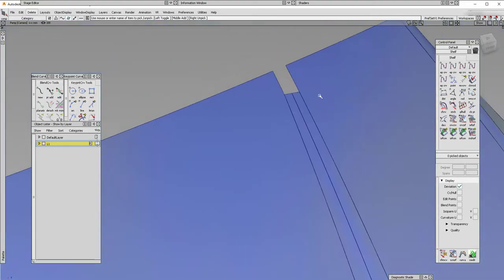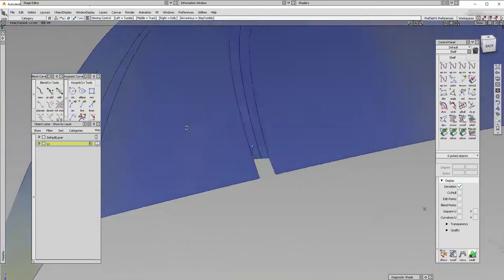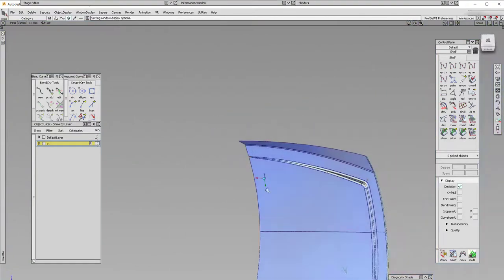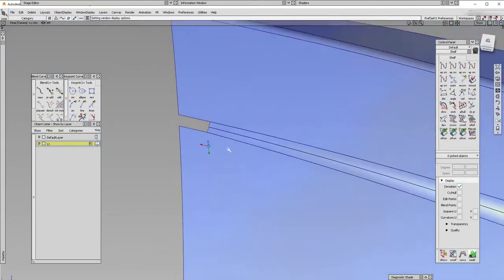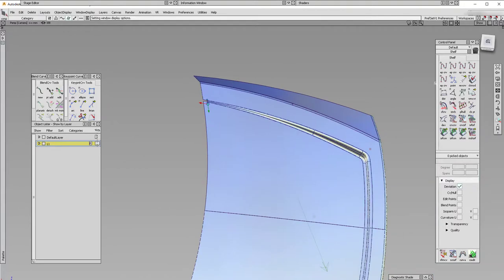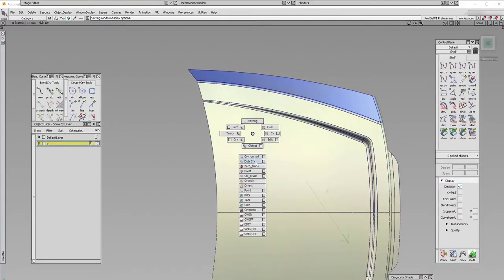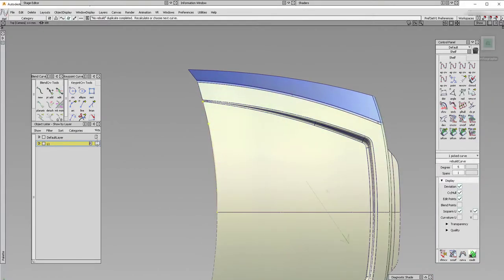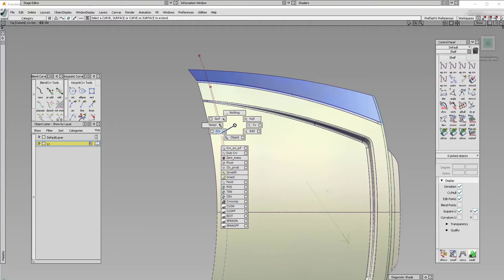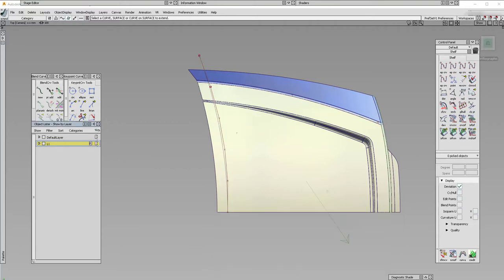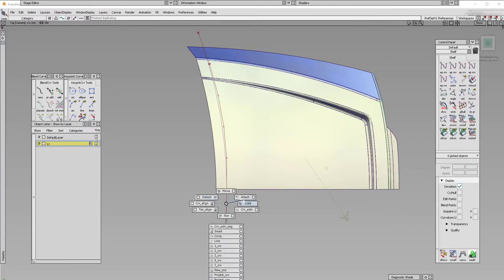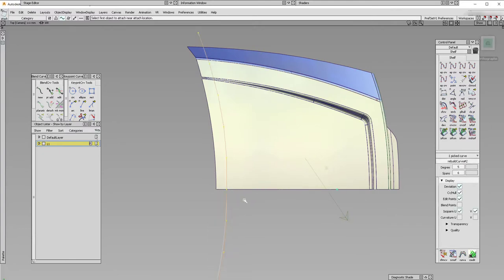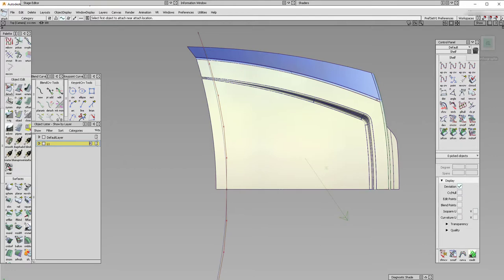There is an issue here we need to solve, and you know what, I'm gonna cheat. I'm gonna be cheating this one. I'm gonna do that. Duplicate this curve, move this a little bit like that, extend this, duplicate on the y-axis, attach these two curves together.